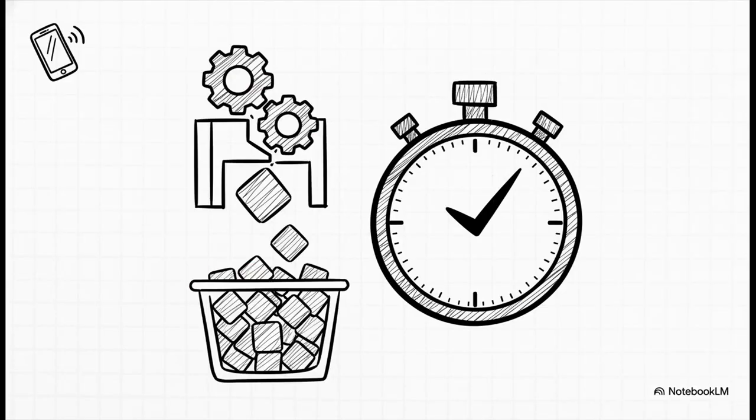So here is the absolute crucial point, the heartbeat of this whole thing, the MAC operation, multiply and accumulate. Because of the CALU's dedicated hardware, the C5X can multiply 2 numbers together and add the result to the accumulator in one single clock cycle. It's the digital equivalent of patting your head and rubbing your belly at lightning speed. This single cycle capability is the true secret sauce that makes this chip absolutely perfect for high-speed signal filtering, like instantly cleaning up the audio on a cell phone call.